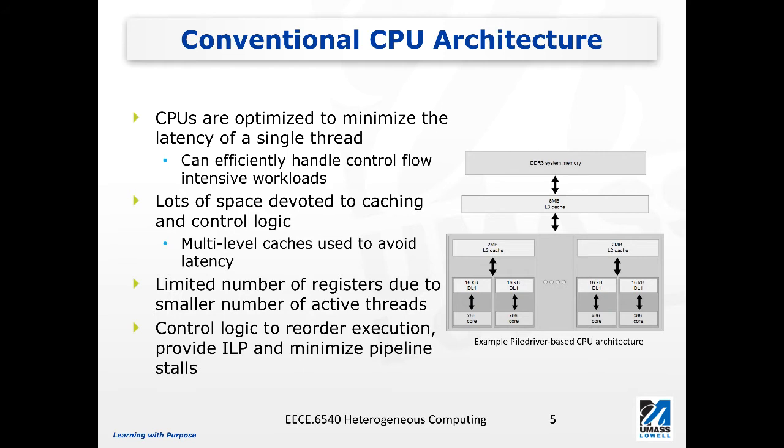These chips typically have a limited number of registers due to the smaller number of active threads that will be running on this chip. And the control logic is devoted to reordering execution, providing instruction level parallelism, and minimizing pipeline stalls.